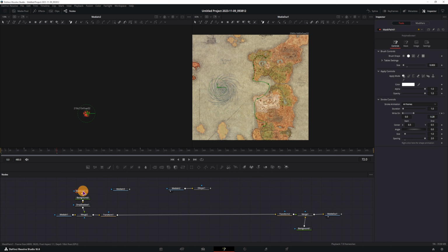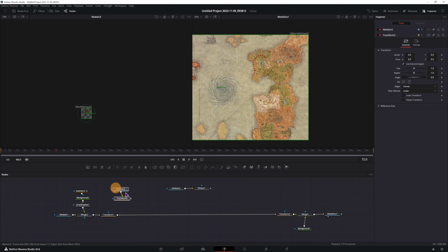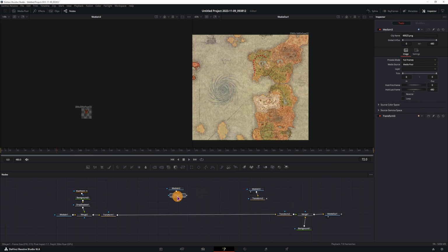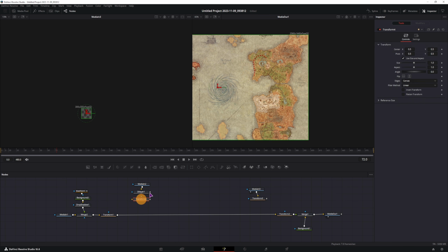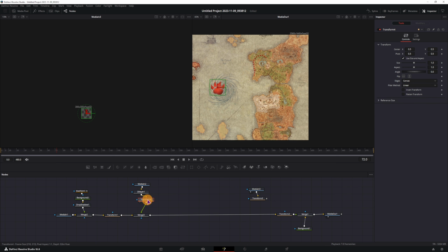What you'll do is select the mask paint node, right click here for a shape animation. So let's do that. And we'll click publish. So we get the polygon or the path of this shape. And for these images, we'll now need the transfer node. So this one will be at the end, I'll put it here, and this will be at the beginning. A transfer node here, I'll connect it to here. With this transfer selected, we can go to the center, right click and click on path, because we want to connect it to this path that we made.